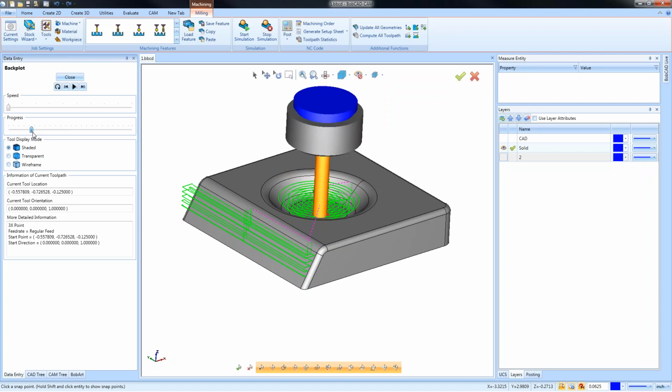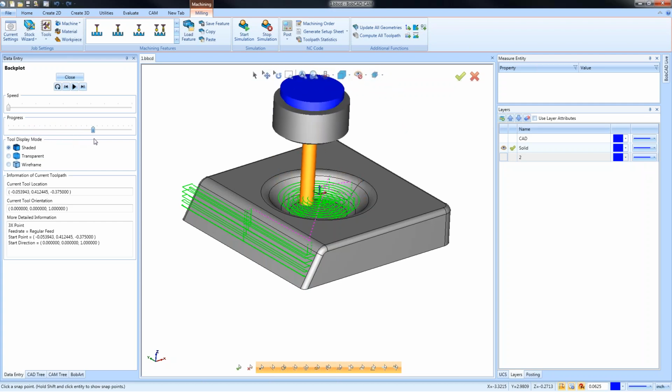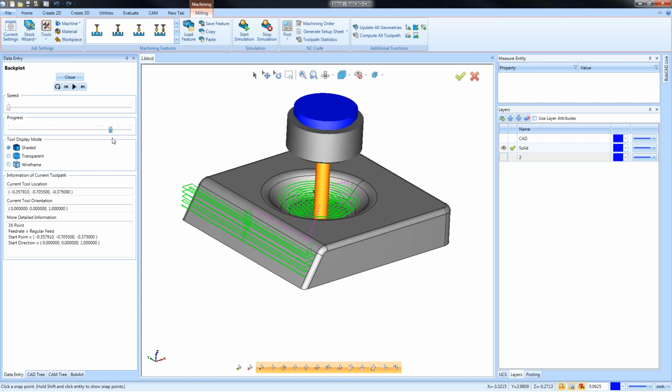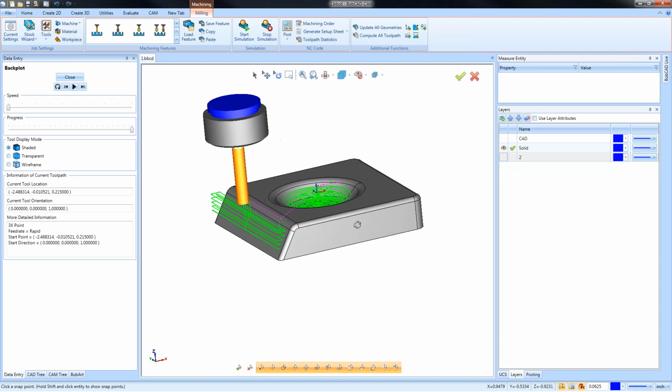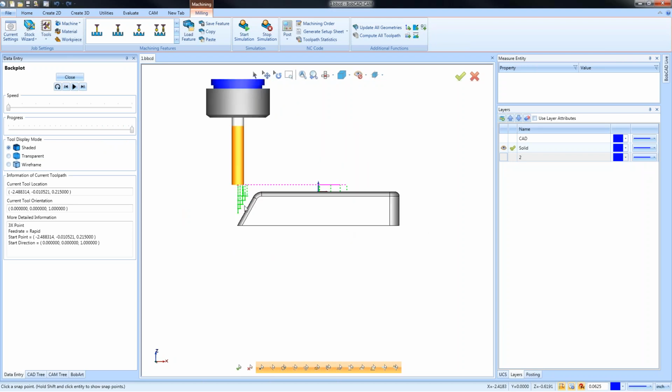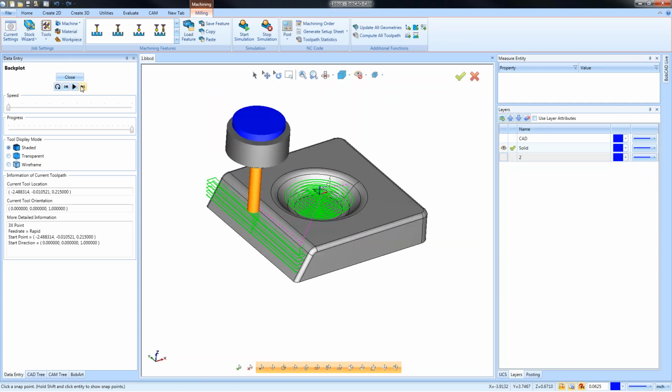And then it also uses the stock as a boundary. Okay, so if we look at this toolpath here, essentially we're doing a pocket on the inside shape, and then it's doing a pocket on the outside shape. And because it's 3D, it's going to follow the slope and curvature of the model. Okay, so that's what we're looking at. The first one is a 3D pocket.